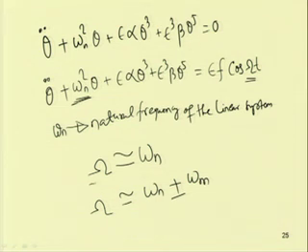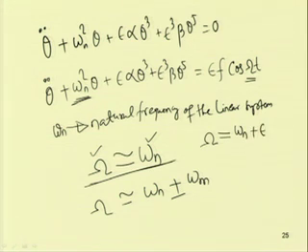So, in the first case, that is when omega is nearly equal to omega n, to study the nearness of this external frequency to that of the natural frequency, one can use a parameter, that is known as the detuning parameter. So, one can write omega equal to omega n plus epsilon sigma.